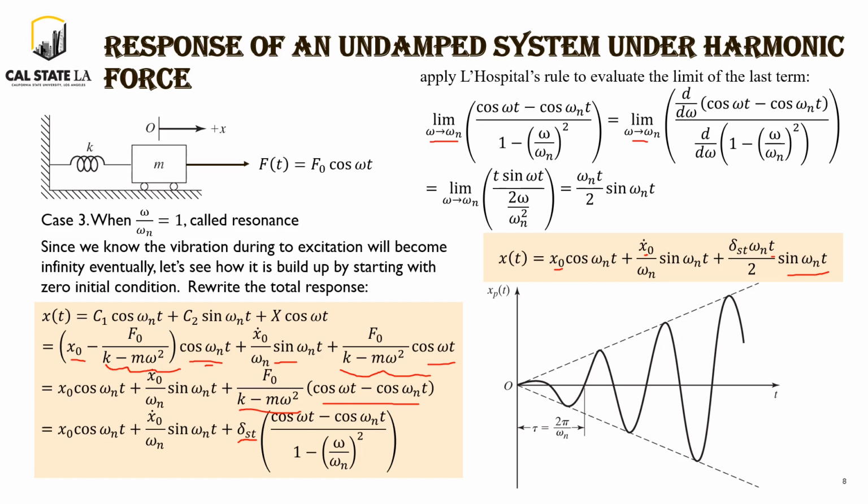And we also know that all these three terms have the same frequency. So it means they are synchronized harmonic motion. The summation of them will also be harmonic motion, but with a different phase angle. If we plot that out using the time domain curves, you will have a similar shape, but started with a different phase angle.